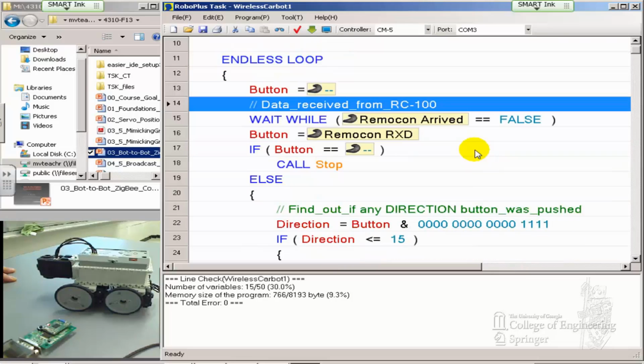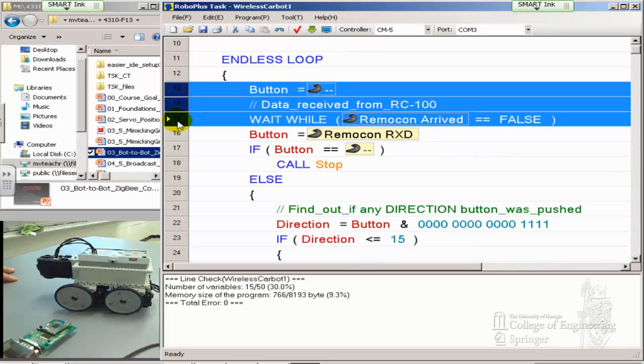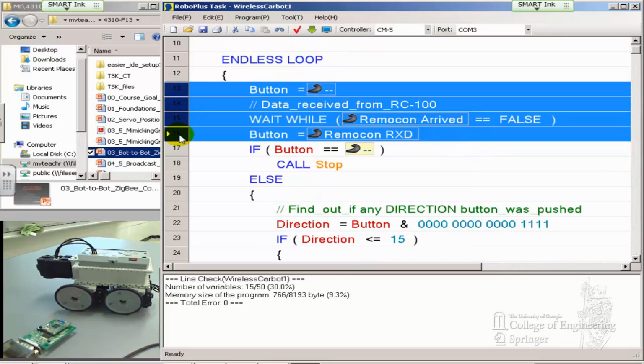All right. So go back. This is a proper procedure when you do remote control. Always clear whatever data you have. Wait until you make sure you receive really fresh data, and then start processing it. And then you don't have the problem of it missing a packet or missing a command, which could be crazy in RC control. Question? Yeah. Yeah, mine's not working.